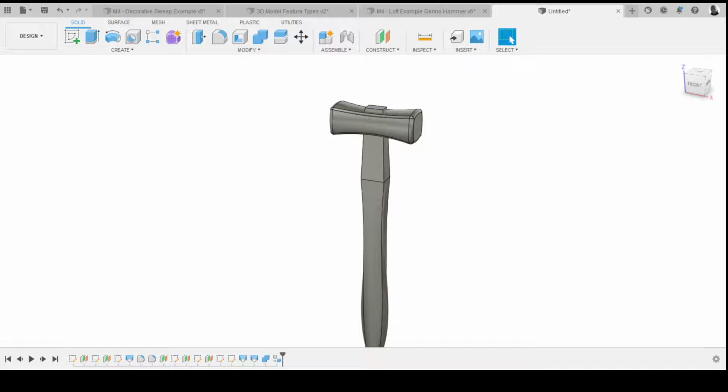And then it'll just create this component, Component 1. I'm going to name it by a slow double click on that text box and call it hammerhead. And then do the same thing for, in this case, Body 4. Right click on that, Create Components from Bodies. That's Component 2 in the browser. So if you look here under Bodies, right click on that, Create Components from Bodies. And a slow right click on Component 2 will enable you to change the text.